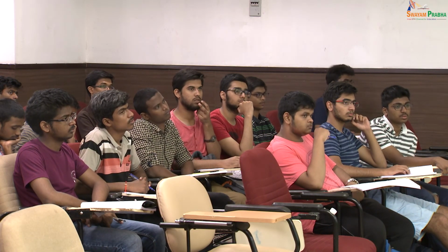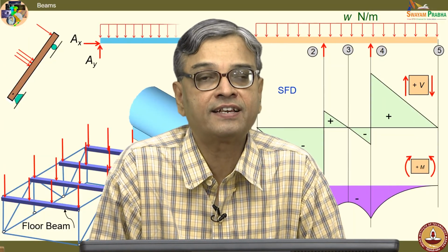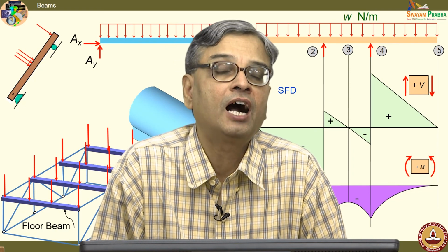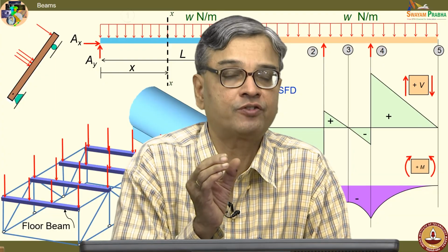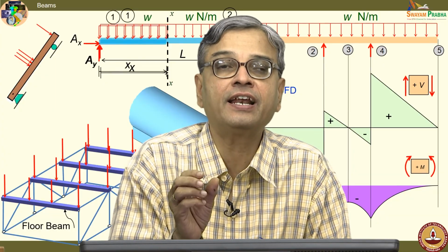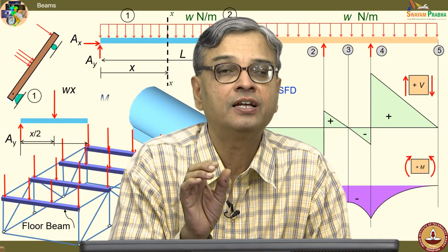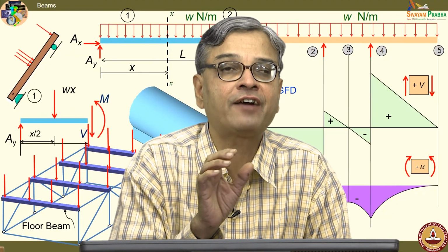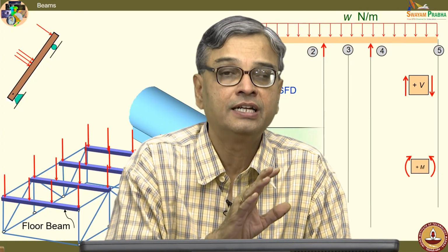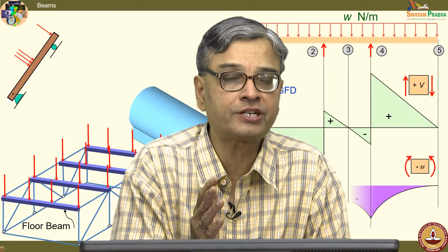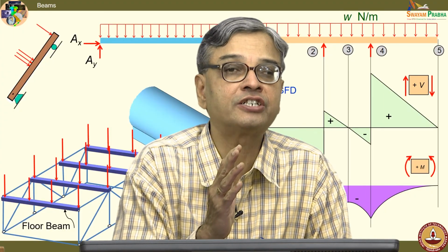So, in this lecture, we have looked at great length at what a sign convention is, and how the sign convention influences the free body of the isolated section of the beam. We have seen very clearly the final free body remains the same when the forces are indicated correctly after the mathematical calculation. However, plotting of the shear force diagram and bending moment diagram depends on the sign convention adopted.